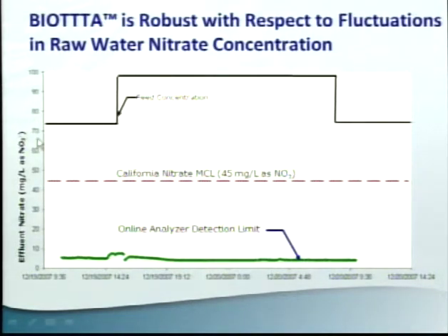What we were coming in at here at 75, for most of the study, then we spiked in an additional 25 milligrams per liter of nitrate. In that case, we just adjusted the acetic acid to account for the additional nitrate removal. Didn't change any of the contact time, and you see that there was no blip at all in performance. And this wasn't that surprising, because as you measure that nitrate concentration down the depths of the bed, which we run with about a 5-foot bed depth, we see the nitrate removal happens in about the top 18 inches of the bed. So it wasn't surprising to us that we had additional capacity at the bottom of that bed.